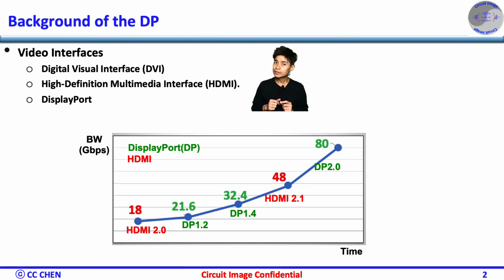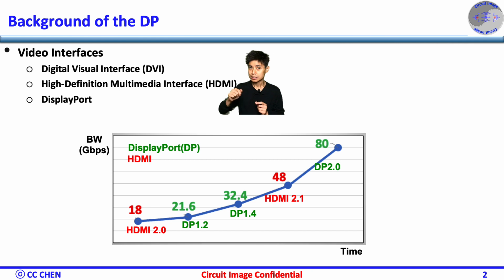The original common video standards for computers were Digital Visual Interface (DVI) and High Definition Multimedia Interface (HDMI), but both standards apply high voltage drivers and receivers under a DC coupled serial link in the interface. What could be the issue of the high voltage for higher PPA requirement? Correct. To achieve high performance, low power, and low area, we may need the most advanced technology, but it decreases the supply voltage as the process geometry shrinks.